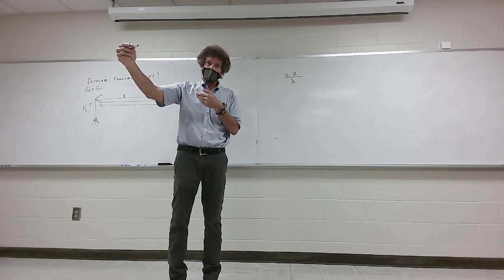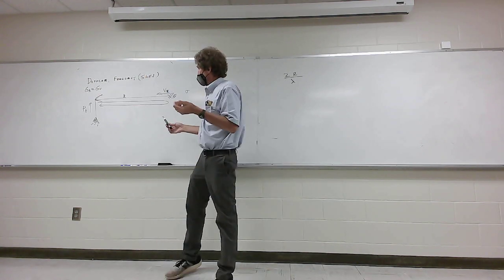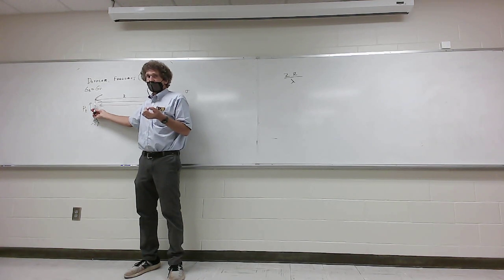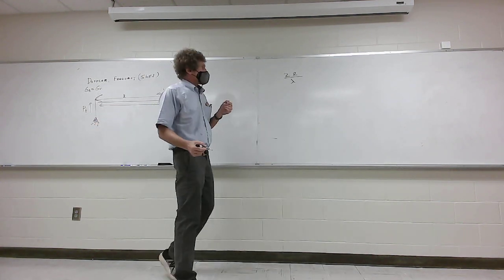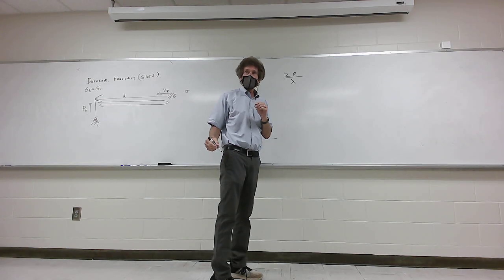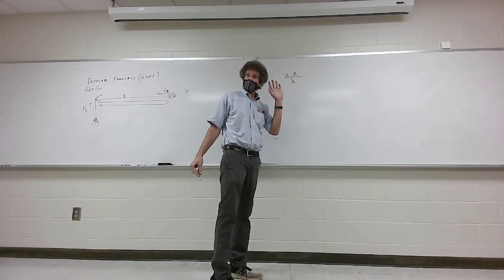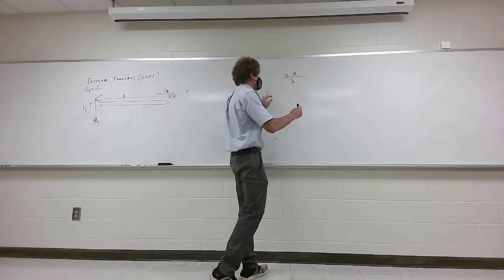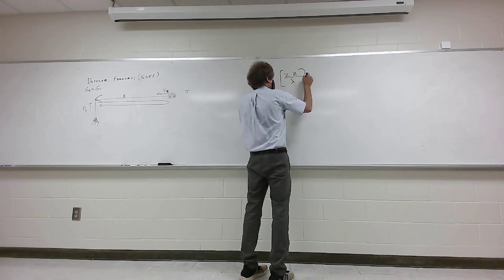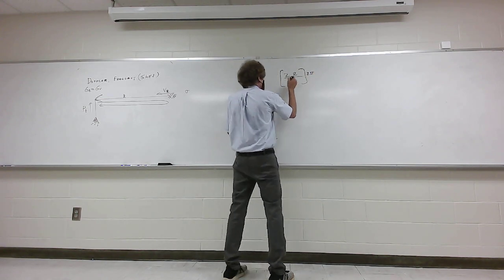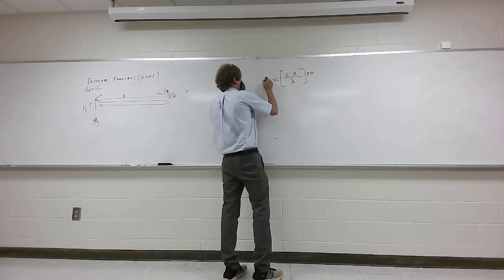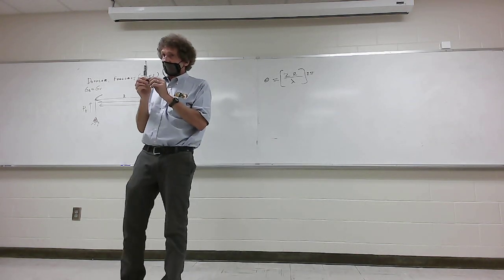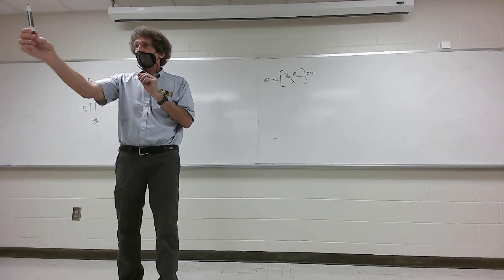Do y'all follow me on that, class? Just freeze time. That's how many wavelengths would be from here to here. Agreed? Now, each one of those wavelengths, this is the number of wavelengths that are actually involved in this round trip. When we multiply these by 2 pi, now I get the total phase that the actual signal would change from the time it's transmitted to the time it hits and reflects back.